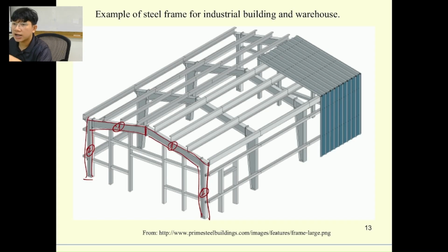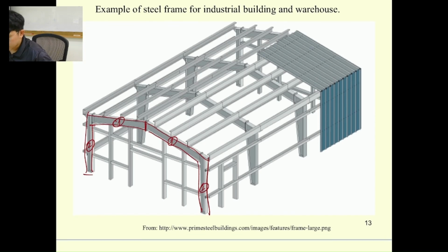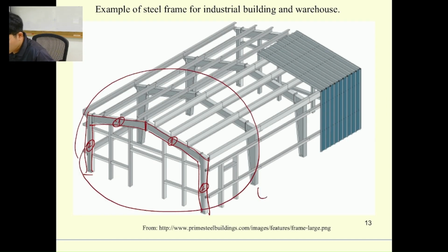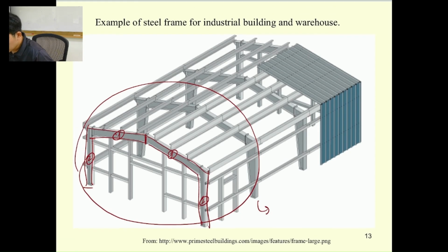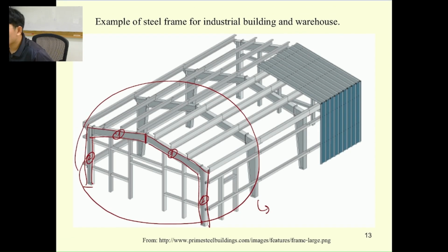They just repeat it, and everything is going to be much faster than doing it at the site. All of these are structural steel. Most of it uses hot roll steel, from TIS 1227. But for the metal sheet, which is the roofing, it comes from TIS 1228.